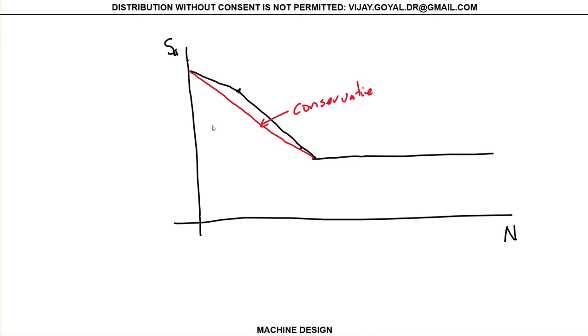Let's suppose I have an equivalent stress that would come here. If I come over here, you can immediately see I'm going to have fewer cycles. Let's call this N1. For the same stress, for the typical curve, I can call it N2. And you can see that N1 will be less than N2, so we are designing for less life.